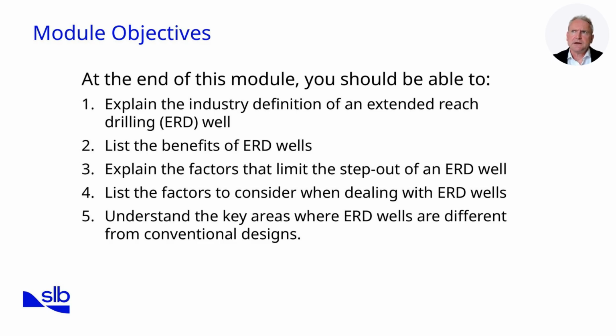We'll then examine equivalent circulating density management. ERD wells face unique ECD challenges due to shallow vertical depth and long lateral sections, making fluid pressure control far more complex. Next, we'll address trajectory design. Unlike conventional profiles, ERD trajectories must account for torque, drag, hole cleaning, and geological hazards. We'll see why a systems-based, bottom-up approach to path design is essential.